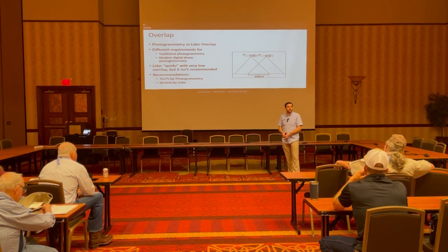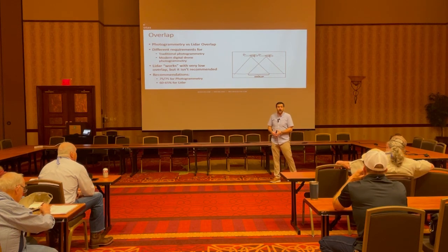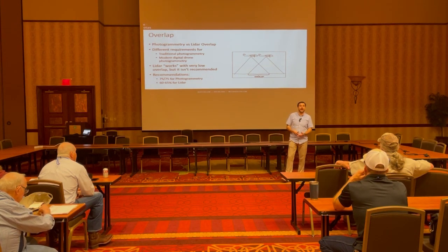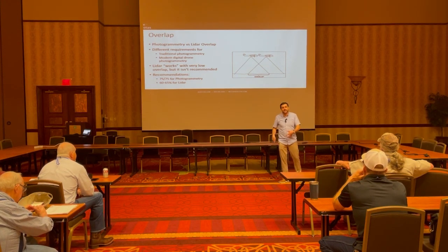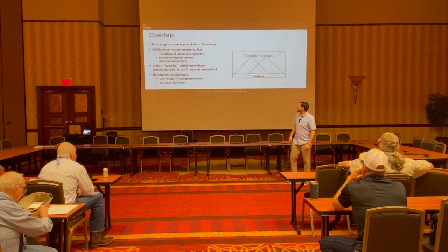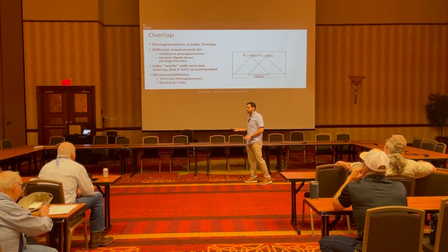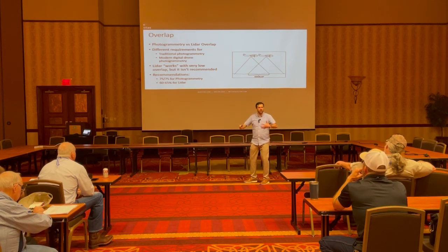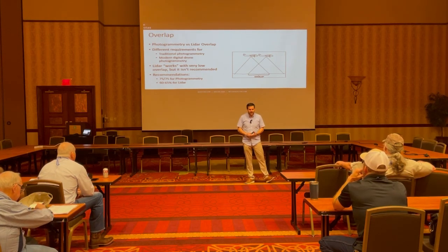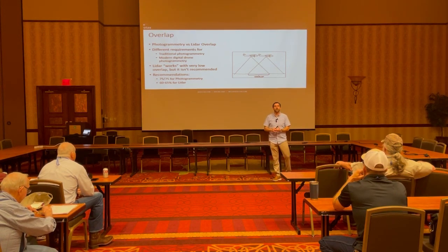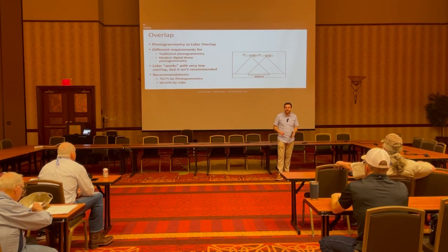With digital photogrammetry, when you are using a couple $100 camera attached to a couple $1,000 drone, more overlap is required to properly internally calibrate the camera on each individual flight so that you can actually get that high quality accuracy. And also, the biggest one, and this is where LiDAR is so much newer to the surveying industry, that this has not reached a level of consensus yet within the industry of what the right LiDAR overlap is.